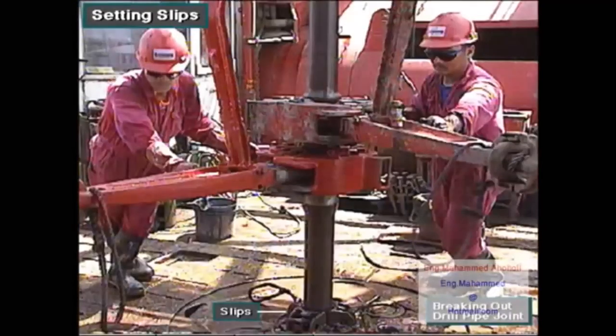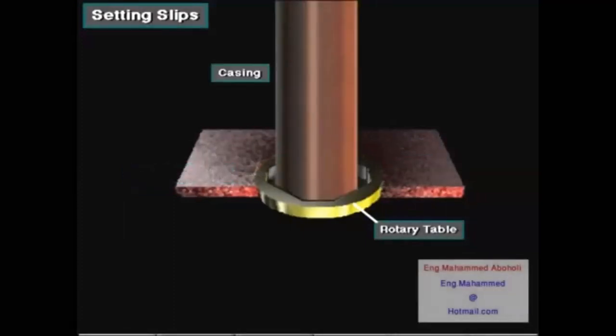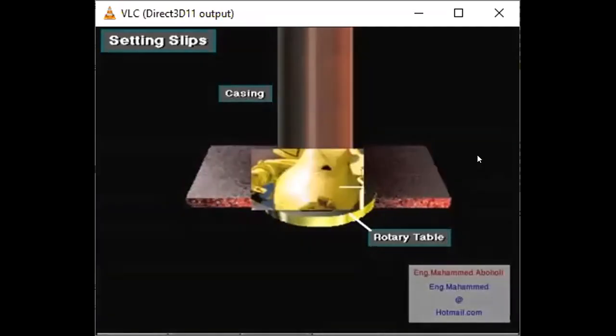Suspending the drill string in this manner allows crew members to disconnect the Kelly or top drive and break out joints of drill pipe. Crew members can remove the insert bowls to provide a larger opening through the rotary table. If necessary, they can also remove the master bushing. They may have to do this to run a large hole opener bit or large casing. Casing is pipe that the crew runs to line the walls of the hole after they drill it.